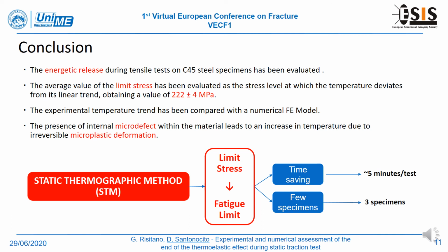An elastoplastic finite element analysis has been carried out on the same specimen geometry and compared with the experimental temperature trend, showing how the presence of internal microdefects within the material leads to an increase in the temperature due to plastic deformation. Knowing the value of the limit stress from a static traction test, it is possible by means of the static thermographic method to predict the fatigue behavior of the material, even with a limited number of specimens and in a short amount of time.